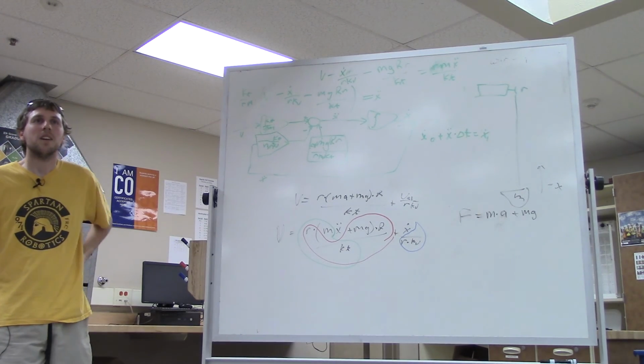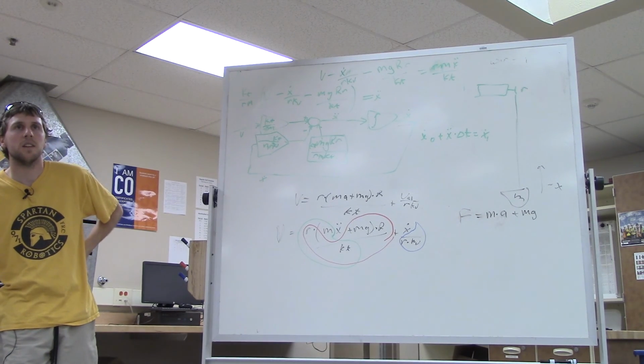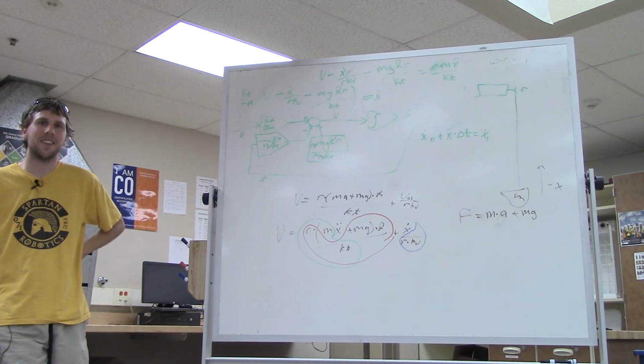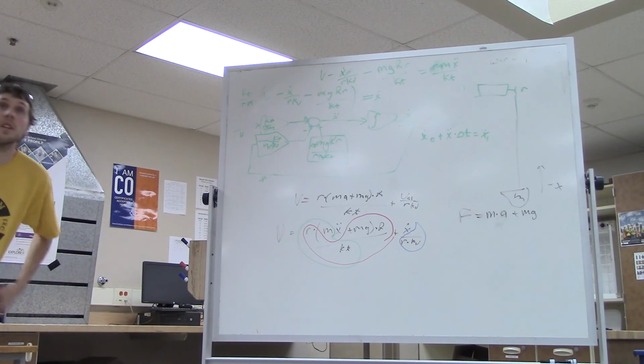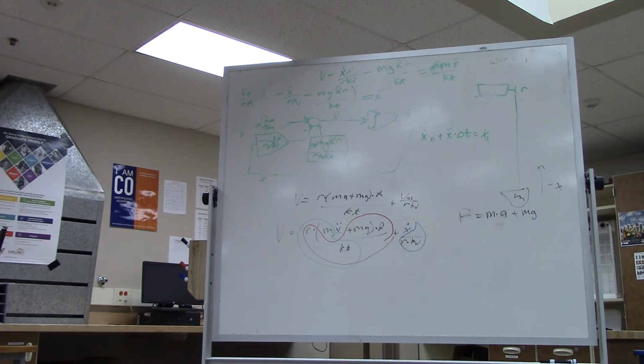Yeah? Some of the data sheets have exaggerated figures. Are there any problems with tolerances or differences between the reported constants and the actual constants when you're calculating KT and KD? So it all depends on how accurate you need your model to be. If your model needs to only be accurate to, say, 10% and the numbers reported are 10%, then you're good. If you want to get better than 10%, and they don't always give you these figures, right? If you want to get better than what you think the error bounds are, then you need to start doing your own measurements. You can measure all these coefficients, right? And go compute a better one.